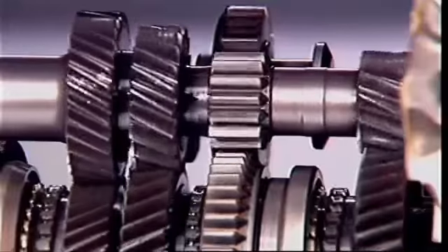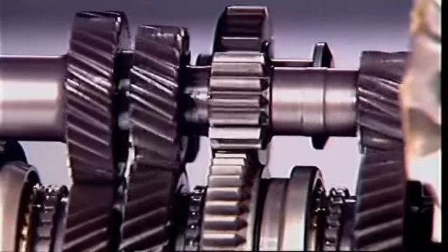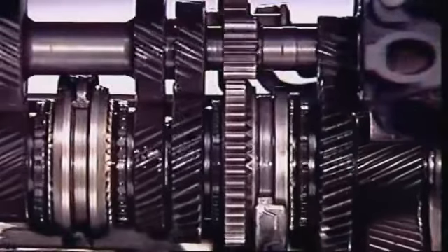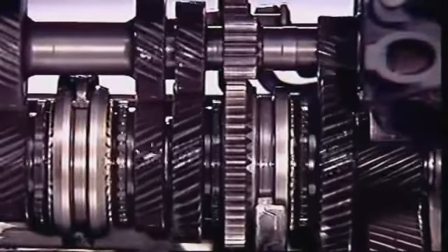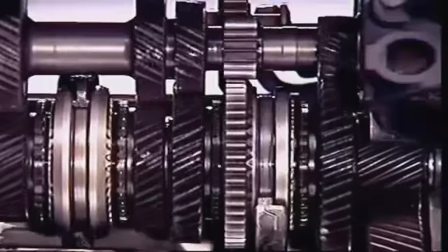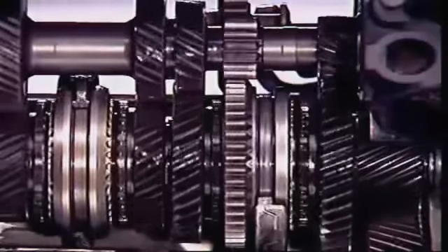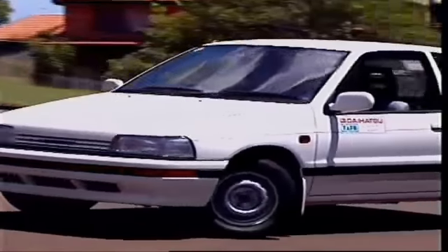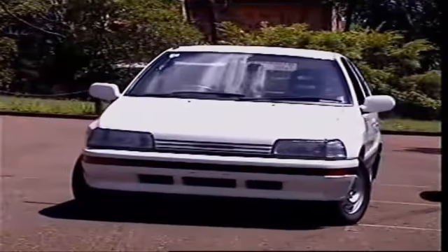Drive transfers through the idler to the spline secondary shaft sleeve. The idler between the shafts makes the secondary shaft rotate in the reverse direction. This reverses the direction of the final drive ring gear and the road wheels.